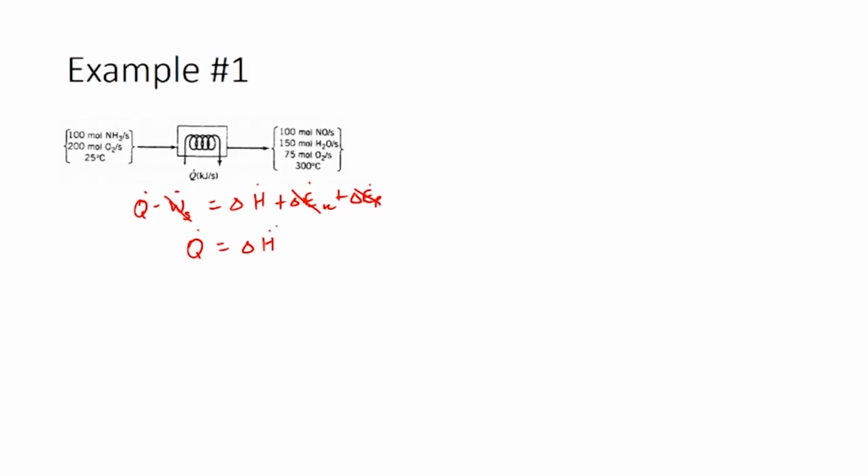Here we have a single reaction and the heat of reaction is given, which means we would prefer the heat of reaction method. So, as I had already said, if we are going to use the heat of reaction method, we would have to use the components in the reaction equation as the reference state. So, as the standard heat of reaction is given, we will use these components as they occur in the reaction equation, basically the same phase and at 25 degrees Celsius and 1 atmosphere as the reference states. So, let us look at the reference states first.